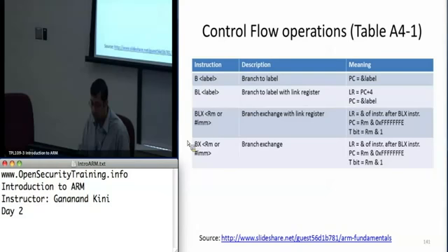And if you look in GDB, you'll see the address is still even. That's because it's actually masking the address and setting it to the PC, but the T bit, which is the thumb mode bit, whether it's in thumb mode or not, gets assigned the least significant bit of the actual address.